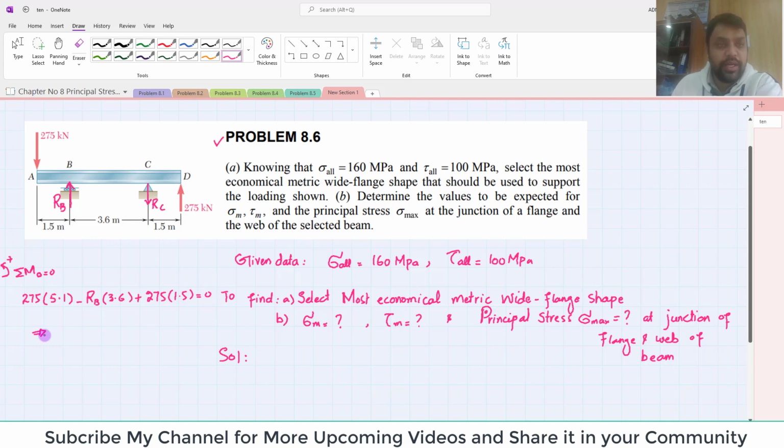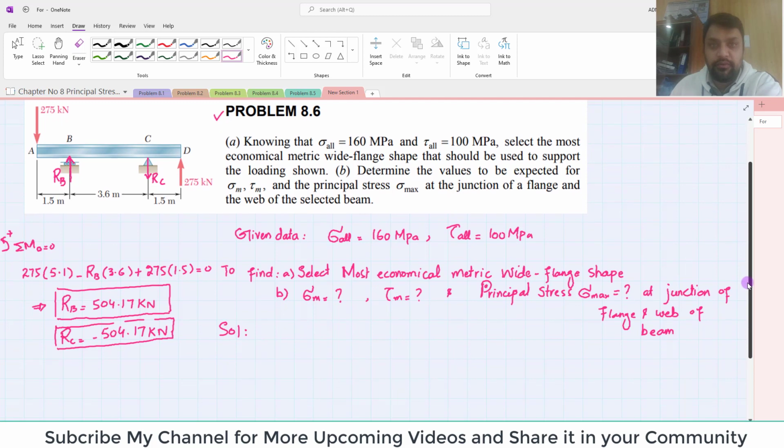So when you calculate it, you will get RB equal to 504.17 kilonewton. You can see this force 275 is downward, this is upward. Clear? So it cancels. For the body to be in equilibrium, RB should be equal to RC, but RC should be downward. So we conclude that RC is equal to minus 504.17 kilonewton.